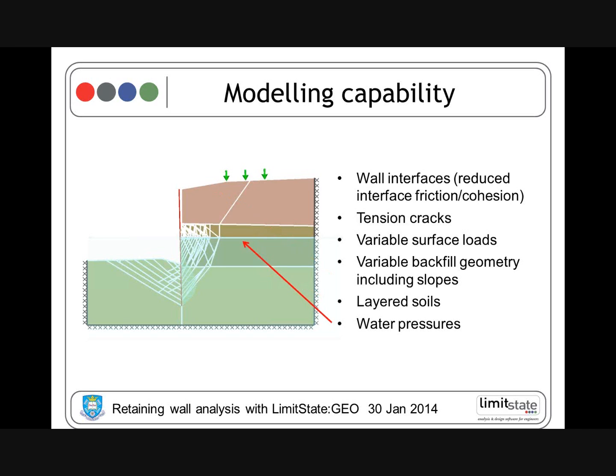So here's just modeled a simple half-submerged wall, but can model a wider range of water there. We're not going to look at detail. There isn't time in this webinar to look in detail at the water modeling, and that will be addressed in a later webinar. But the software can model inclined water tables, different water pressure regimes in different parts of the model, or you can import water pressure distributions from other software to model, for example, seepage type water pressure distributions.